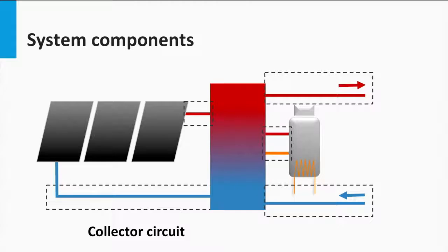The flux can either be caused naturally by the temperature gradients, forced by a pump, or by a heat pipe, in which the fluid is allowed to boil and condense again. The best choice will depend on the specific system considered. Also, it must be taken into account that if the pipelines are very long, the losses here can be considerable. So pipeline length would have to be minimized.